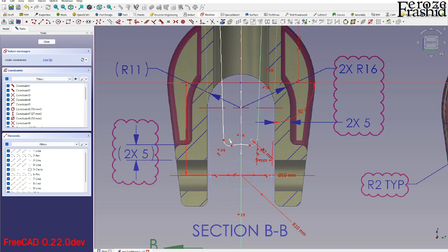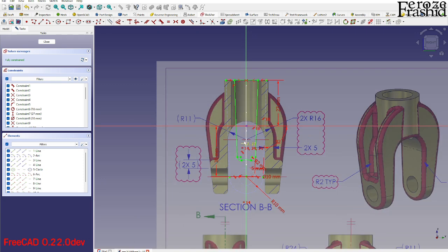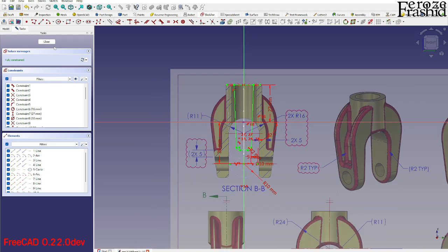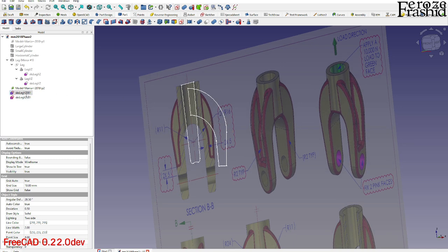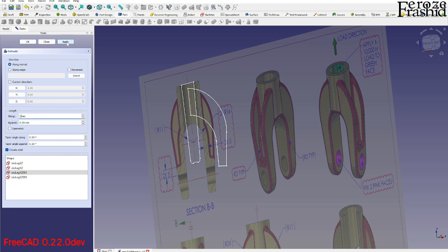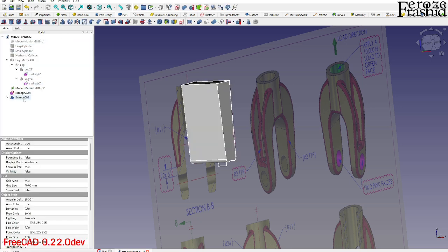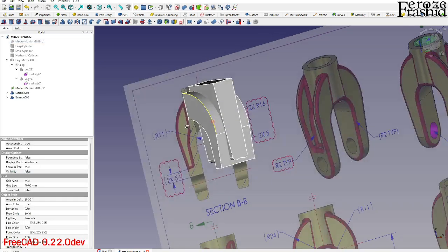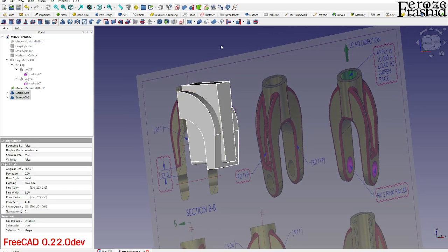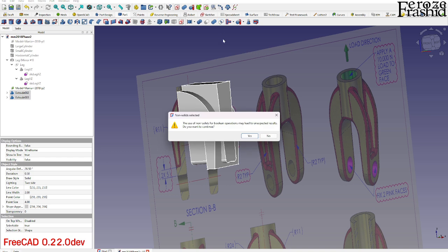And maybe make these two on the same horizontal plane. That fixes it. All right, so what we have here is a smaller arm, so we'll do the same thing. We'll extrude this one outward, say 25 worked last time, so we'll go with that, and this one will go with 25 as well, but it will be symmetric. And now I can go ahead and make these two an intersection.